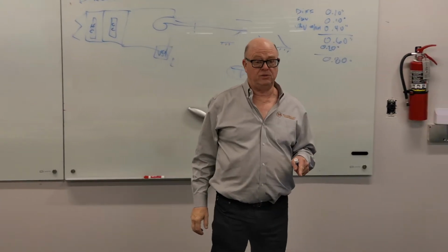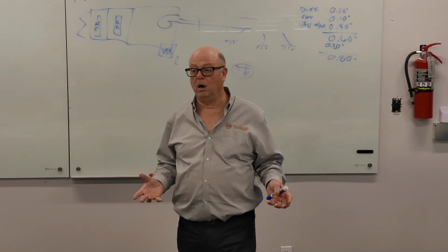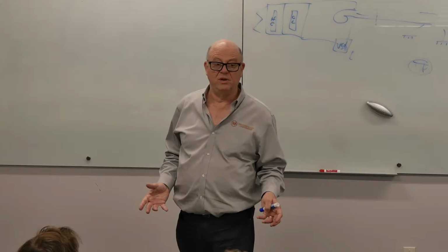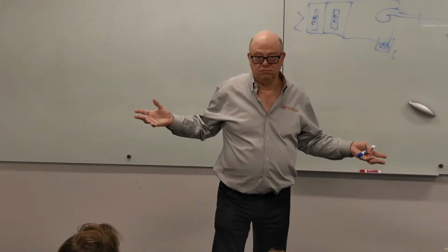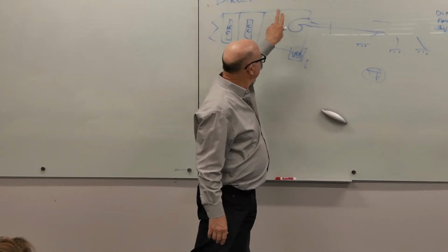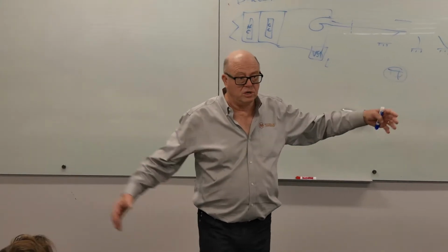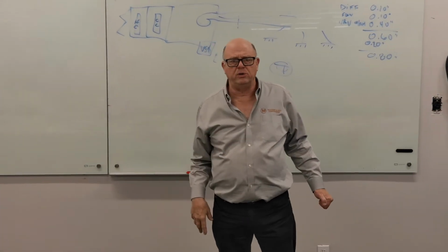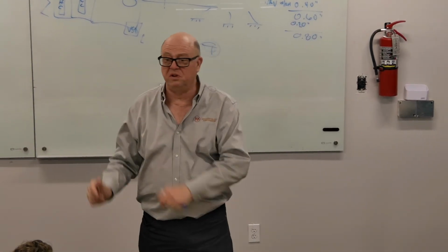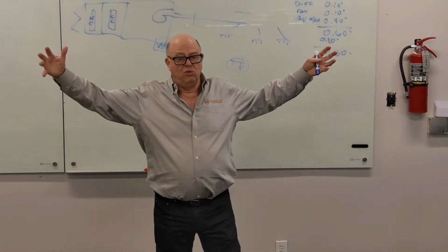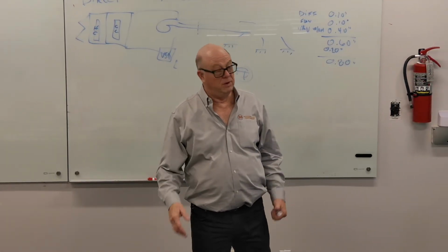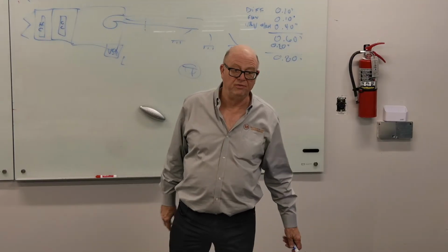With the LED lights, the heating load in an OR is like less than half of what it used to be. The driver now is probably the ventilation air in terms of load. Okay, so that's the little speech. Single zone VAV. And if you go single zone VAV for a barn, but you got one particular area you're concerned about or two, go with a little bitty single zone VAV. Or if it's small enough, just a little constant volume fan coil. But if you can do the bulk of the room with single zone VAV, it's also very efficient, but it's definitely the least expensive way to go.